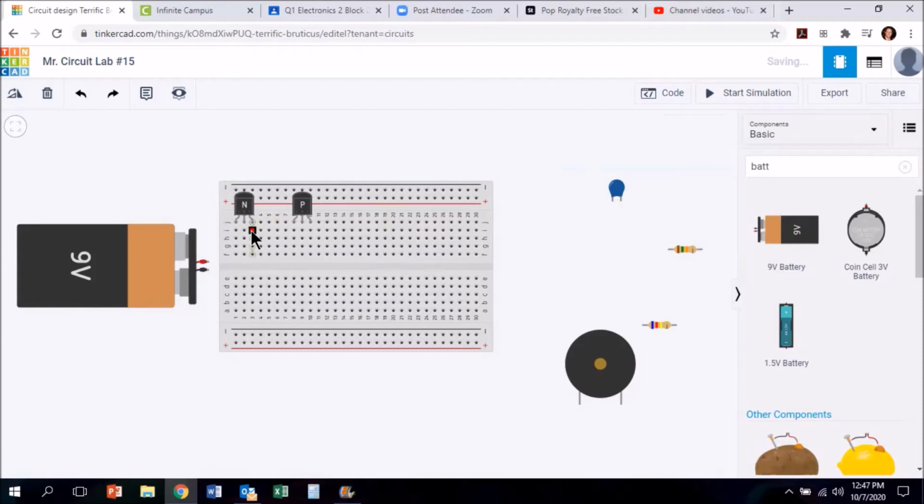Now we can make a connecting wire between these two first. Go from the third lead of the NPN transistor to the middle or base lead of the PNP or Q2 transistor.